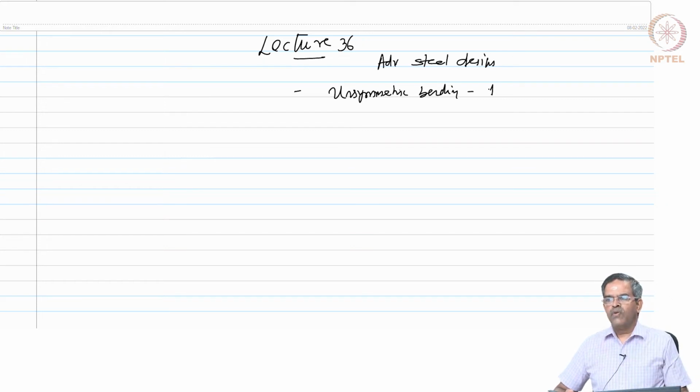Then for form dominant design, we understood that stability, which is one of the modes of failure, is important to assess, and we developed stability functions for various application conditions of axial compressive load, axial tensile load, and so on. And we did some problems and used MATLAB intensively to find the critical buckling load so that I can assess stability of these systems.